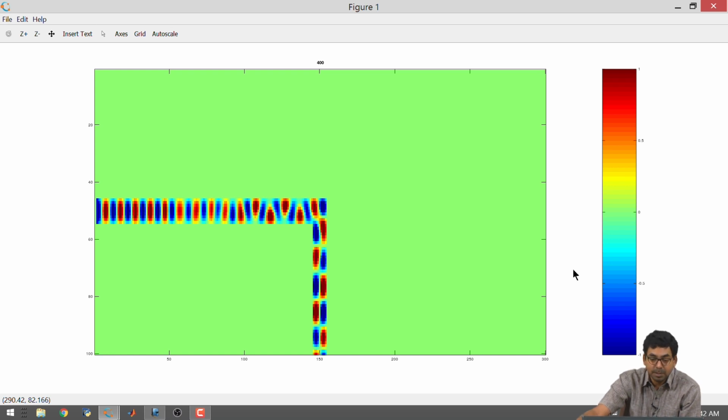Okay. So this means that when you take a waveguide and when you make a bend on it, all right, you will start seeing the modes that are present. The second thing that you are noticing, which is more interesting, is that we launched and the pattern appeared to be predominantly fundamental mode. Fundamental mode had one spot. The fundamental mode did not pass through this abrupt 90-degree bend, all right, which means that it may have hit this wall and it is getting reflected back in the horizontal section and it is creating an interference pattern.